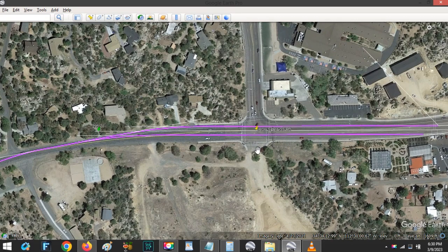The IND subway in New York comes to mind, where at 34th Street and 6th Avenue, the line dives under the 31st Street tunnel from Penn Station, which is a two-track tunnel, two tubes, or I don't know, it might be an open caisson arrangement there. Dives under it. It's customary to build new tunnels under old ones rather than from above, because it tends to cause disturbances if you build above. So that's what they did.